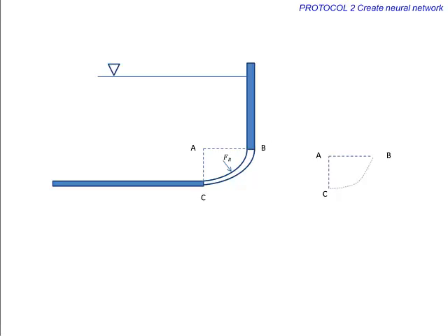Imagine that this fluid is in static equilibrium with a number of forces acting on it. Force F1 acts on surface AC from the fluid to its left, force F2 acts on surface AB from the fluid above, and W is the weight of the fluid element. The resultant of these three forces will be F_r. In order to balance this fluid element, an equivalent reactive force must be developed by the curved surface.